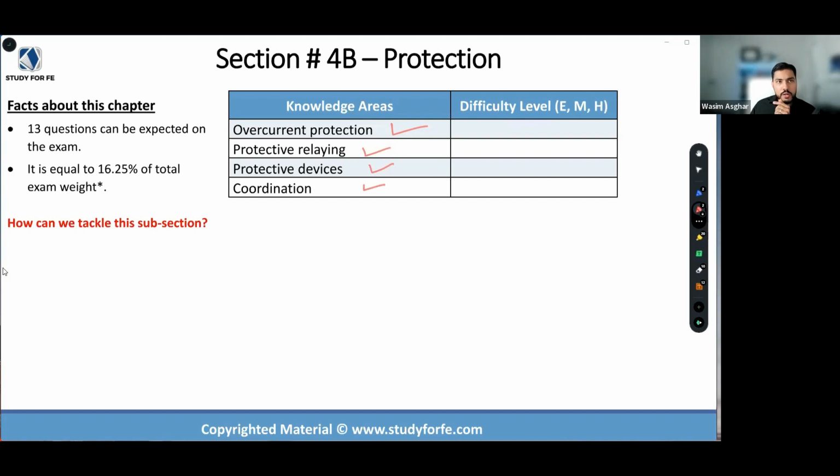And then it's not 100% accurate to say that you don't have any reference for protection on the exam, because NEC is there and NEC does talk about protection, right? Both directly in different articles, for example, motors, transformers, capacitors, and so on, generators, right? And also the catch-all article 240, which is primarily for overcurrent protection, right? But overload is also discussed throughout NEC for different applications. So it's not 100% accurate to say that you're left high and dry, right?